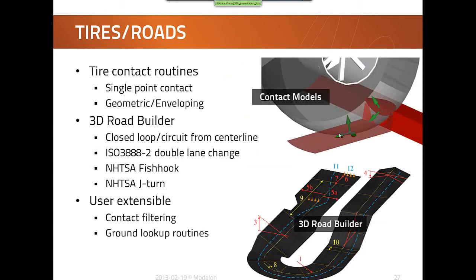And of course, it's user extensible, either through pure Modelica or interfacing to external code such as a DLL. For the ground interaction, there are different tire contact routines. There's a single point contact model. There's also a geometric and enveloping tire contact model that's available.